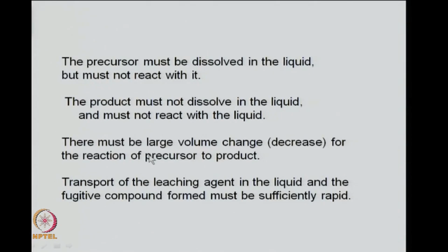The other factor is there must be a large volume change, and typically the volume will decrease because you are going from a droplet to a particle. This volume change should be as large as possible when you are going from the precursor to the product. That helps in the spray pyrolysis. The transport of the leaching agent in the liquid and the compound which is formed must be very efficient and rapid. So, the solvent which is remaining when you are having the particles must be removed very fast from the particle.